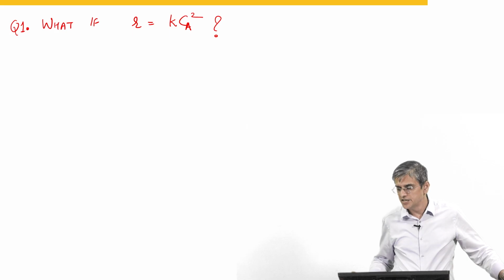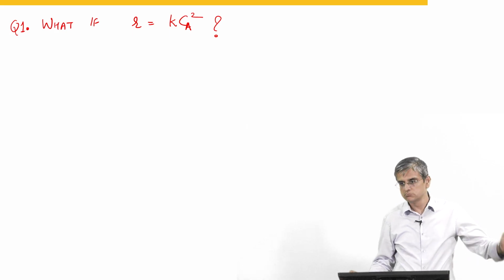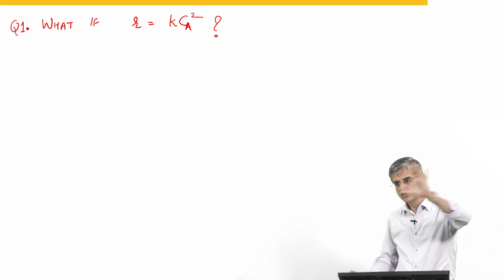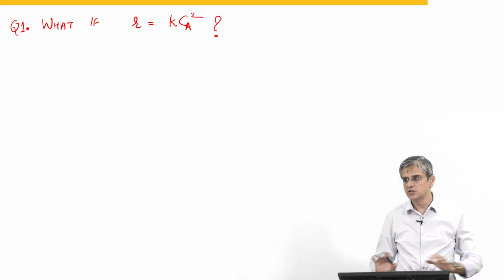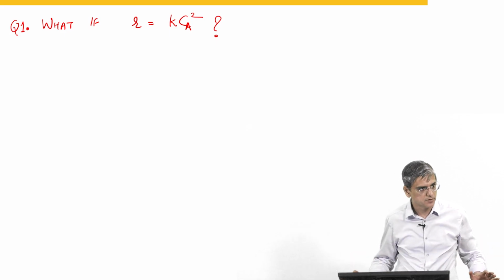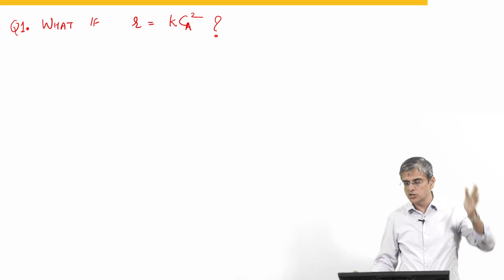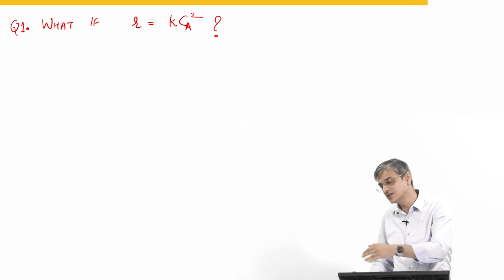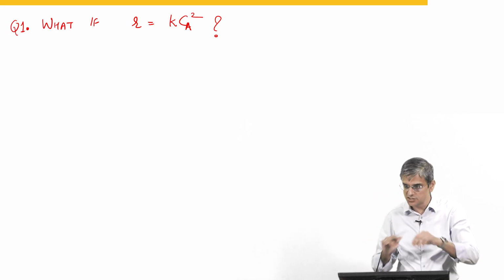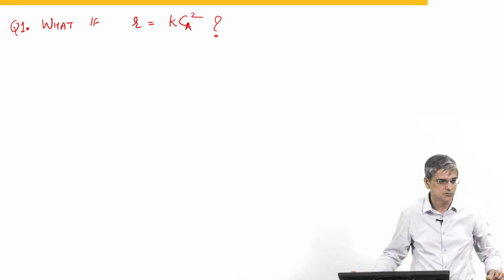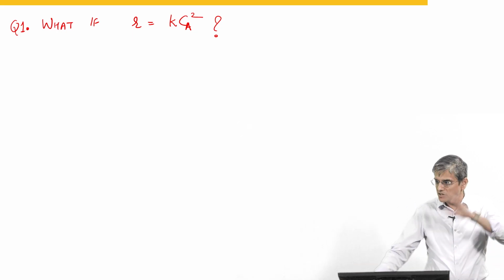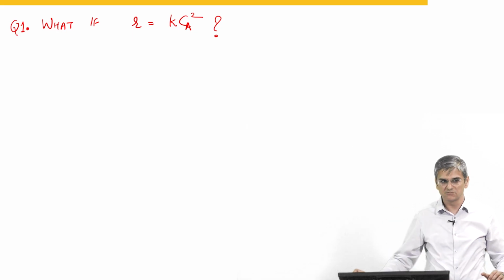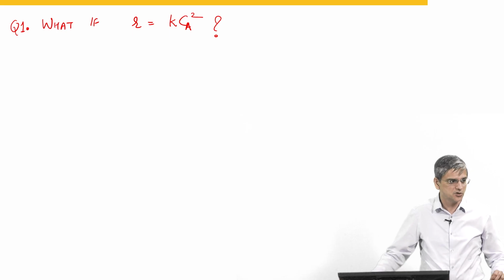If you break down the problem into the concepts, mass transfer to the pellet is one concept, reaction on the pellet is another concept. Because accumulation is 0 at steady state. There is another reason why accumulation is 0: the surface does not have any volume. Remember, accumulation is d by dt multiplied by the amount into the volume of the control volume.